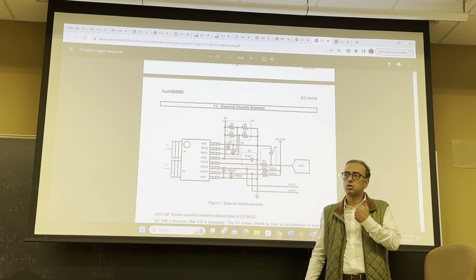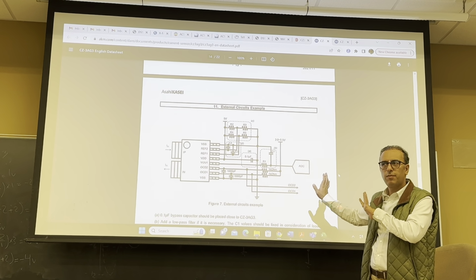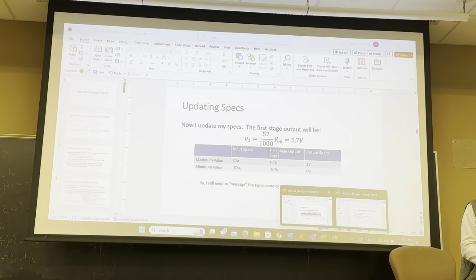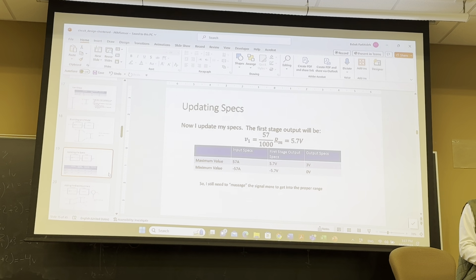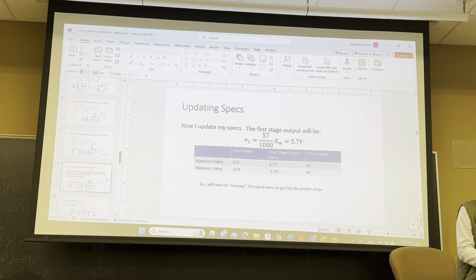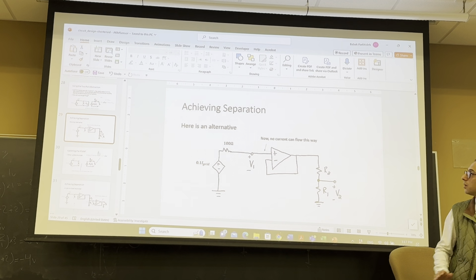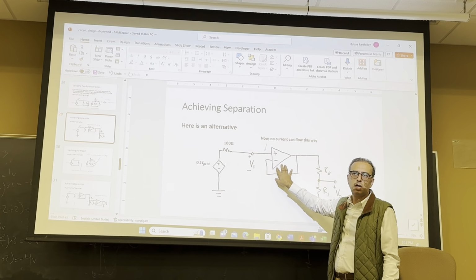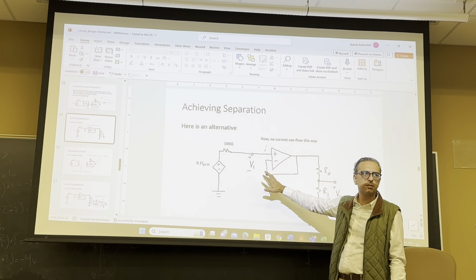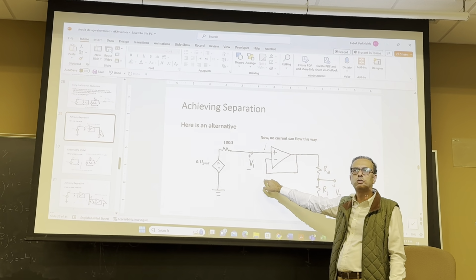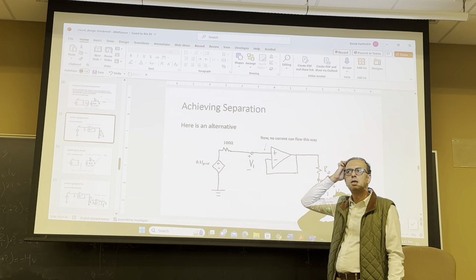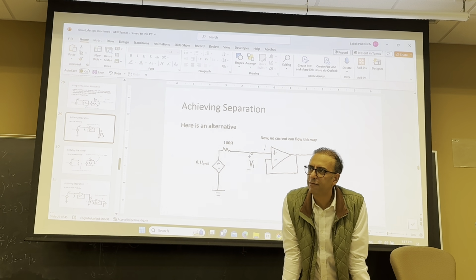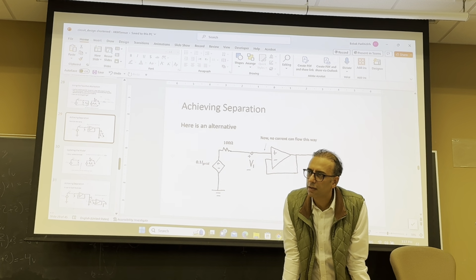So what I do, I use the same thing, don't get me wrong. I may be more conservative and I use a buffer circuit as well, in between. So why did we use a buffer circuit? The voltage follower? Yeah. High impedance output voltage. What's the benefit? It's a cleaner signal.